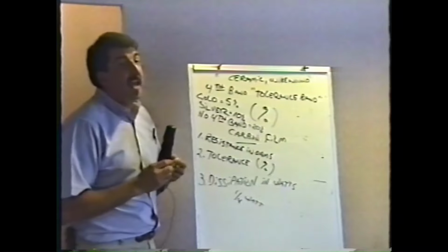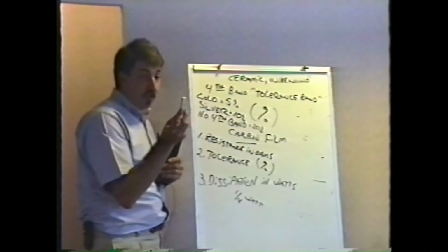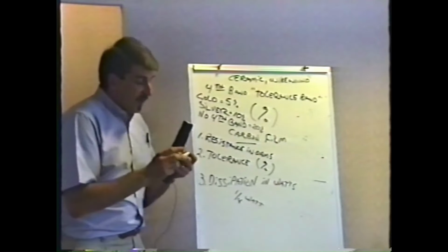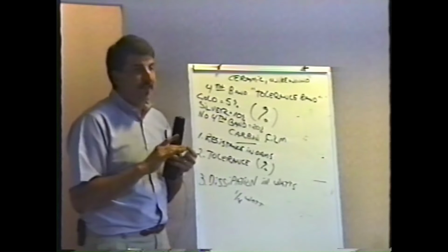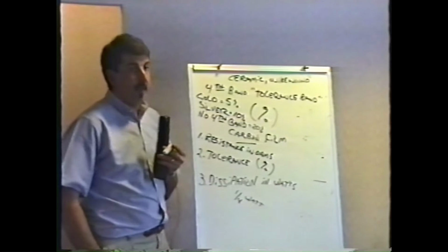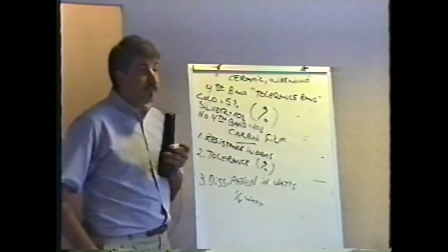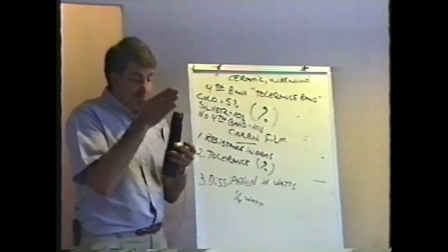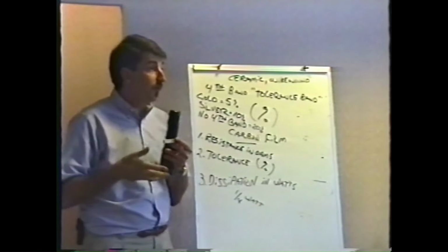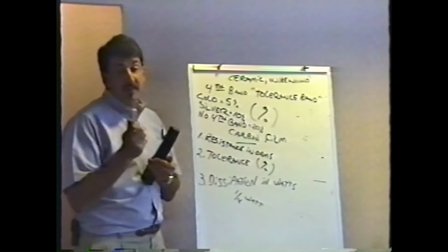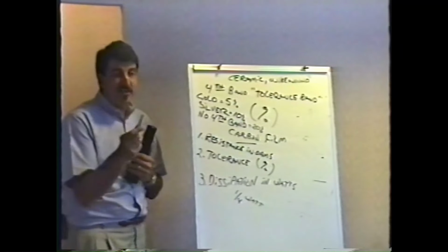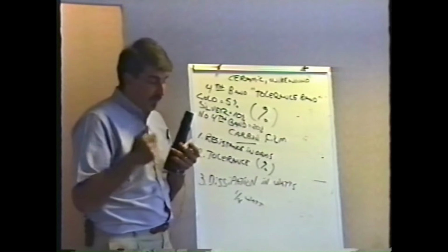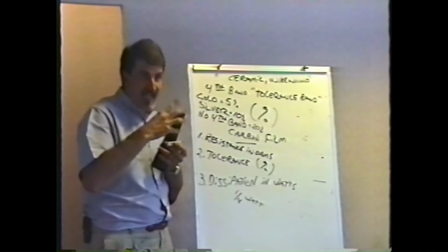They get really hot. In fact, here's a little shortcut you can use to test these things. When I see a big resistor like this, I'll just touch it. If it's hot, it's good, period. Why? Because when resistors fail, what do they do? They open circuit. If the resistor's open, ain't no current going to go through it. It ain't going to get hot, right? Actually, that's the way resistors work. The way resistors resist is they turn the current flowing through them into heat.